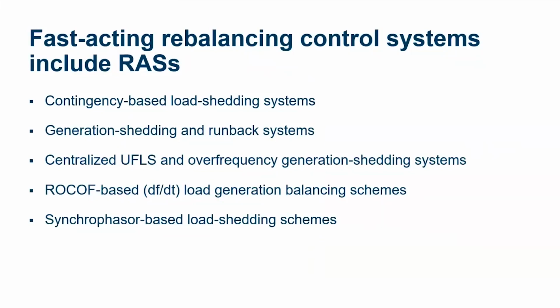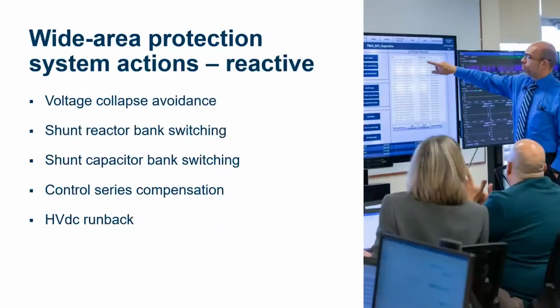Some of the contingencies may be detected using synchrophasor-based techniques, where breaker status may not be reliable or too many to consider. As Mr. Ramesh mentioned, these systems may track system state and can be adapted to adjust their actions depending on system event. For example, if load shedding is required for a given contingency, however, if a RAS system sheds a load that is already offline, it won't do us any good.